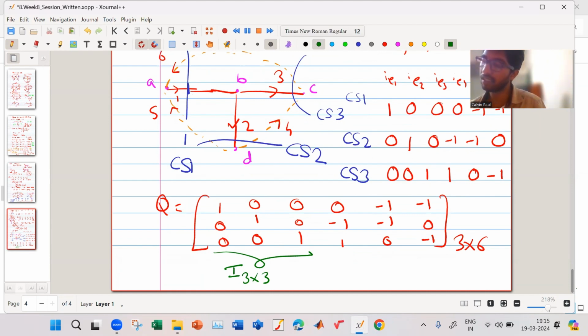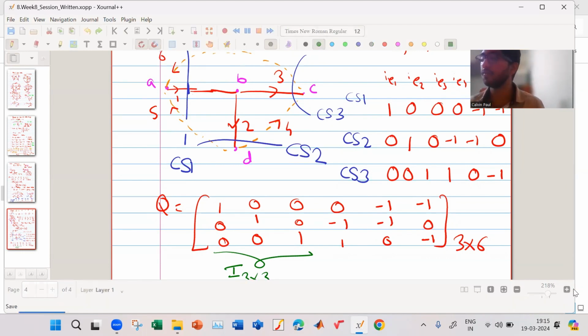Yeah, so that's why it is preferred to use the numbers 1, 2, 3, the first numbers as your twigs, the next numbers as your links. It is the best practice while solving these sums. But in case they have given you a tree where the twigs are 1, 4, 5, then you can't do anything. Then you cannot change. But if you are given the opportunity to decide which are the twigs and which are the links, then you must choose the first few elements as your twigs and then the remaining as your links. All right.